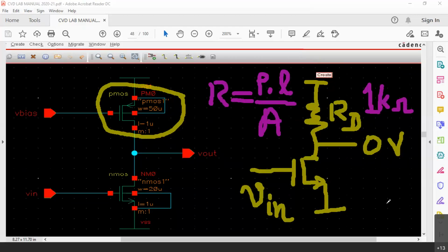So in such a case, whenever we go for manufacturing of the integrated circuits, basically MOSFET is for VLSI. Now, if we directly have to have a physical resistor there inside the chip, we will have to reserve this much of length proportional to 1 kilo ohms, and cross section must be lesser, length must be larger. That means, let me write it below.